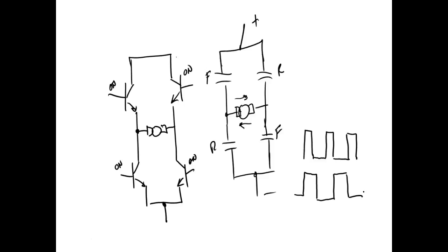So what we can do with solid state is not only control the direction, we can also use this to control the what? Speed. This guy right here, all we do is control the direction. To control the speed, we'd have to change the plus and minus up there. Here we can change the speed without changing the voltage up there. Because what we're doing is we're sending the motor pulses, and we increase the duty cycle, the motor sees it as a higher voltage, which means the current's going to be higher, and the motor's going to run a lot faster. We slow it down.